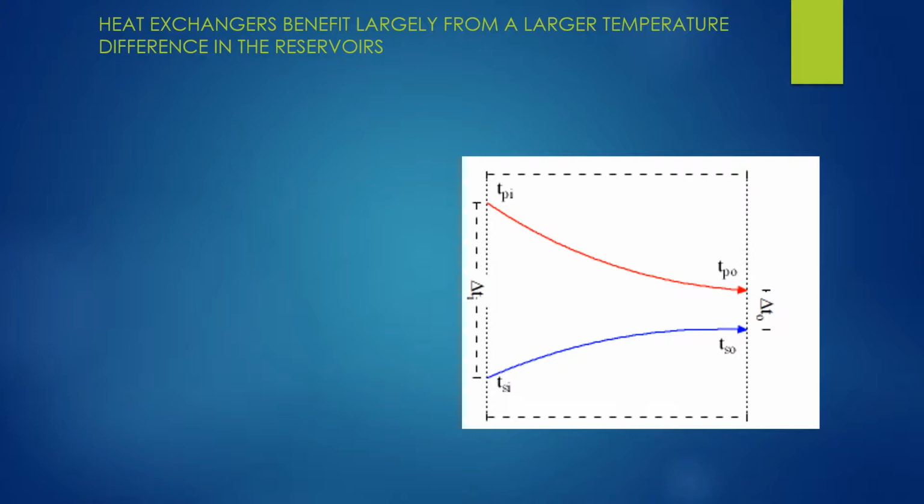This is where the benefits of going in-ground come, because in-ground the temperature is much more consistent and in the middle with regards to the fluctuations of ambient air temperature, which means in the winter it's easier to pull heat from the ground, and in the summer it's easier to put heat into the ground and out of the house.